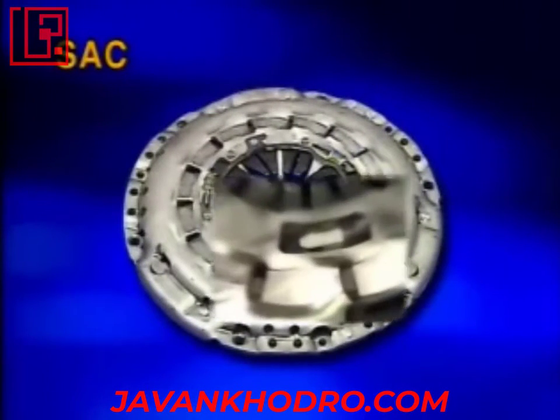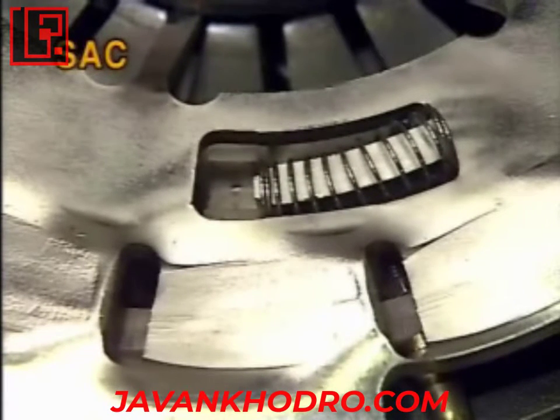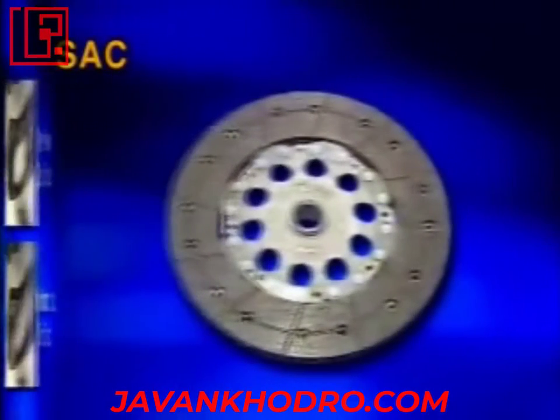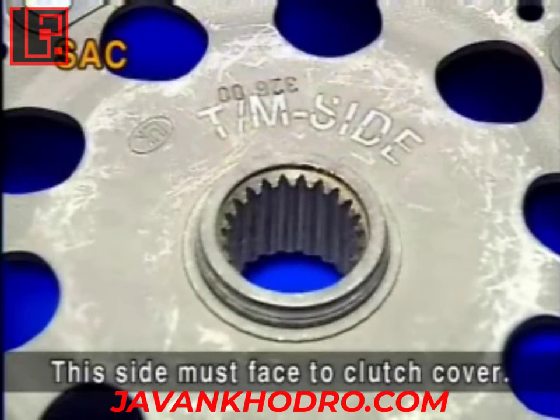To distinguish the normal and worn out one, check the disc wear amount by the spring. The disc wear amount of the normal one is shown at the upper side, and that of the worn out one is shown at the lower side. When installing the clutch, the side having the mark of TM side should be facing the clutch cover.